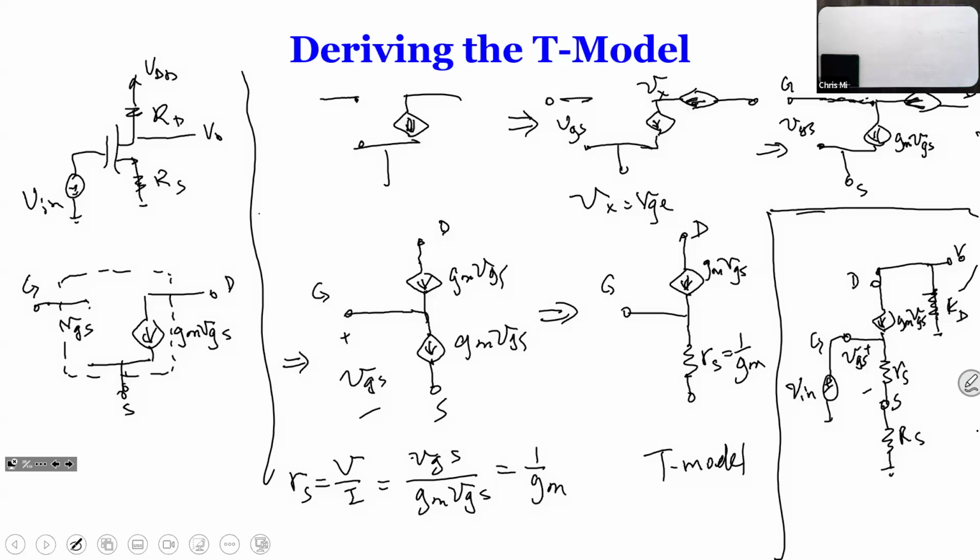So your VGS here and your Vin is across this resistance. So you got that VGS, and you have gm times VGS, you got the current. Now use this current multiplied by your resistance, you got the output. So that's fairly simple. But if you do the previous circuit with the pi model, you're going to have to solve a pretty complex nodal analysis.